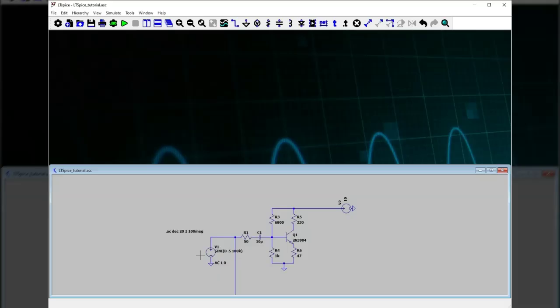The only thing we've requested right now is the AC analysis. So let's request a transient analysis. So how about simulate up here, configure analysis, and now we're going to select the very first simulation type on the top, which is transient. You can't see this pop up, I apologize. And we are running at 100 kilohertz.